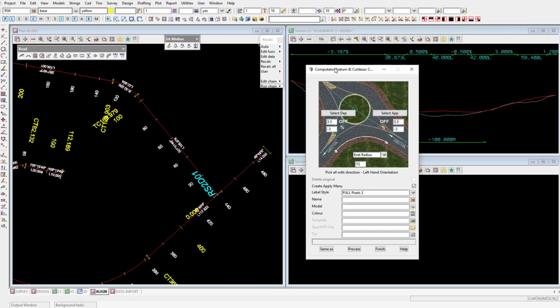So in this case, I know this road here is the approach road because I'm going to create it in an anti-clockwise direction. So I'm going to make this 4.2 meters. Sign is not important in this one, and we're going to the departure road that is 2.7 meters.